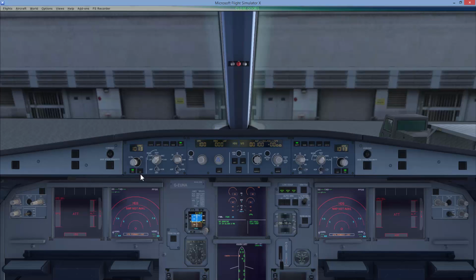Okay, with those pieces of information entered, let's go through the final bit of cockpit prep for me, which is to make sure that LS mode is set to off, that the ND mode and range is set to arc and 10. I'm going to dial in an altitude of 5,000, that's the transition altitude from here, and push that in, push the speed, push the headings so that they're managed by the flight computer, and then close the doors with Shift E.